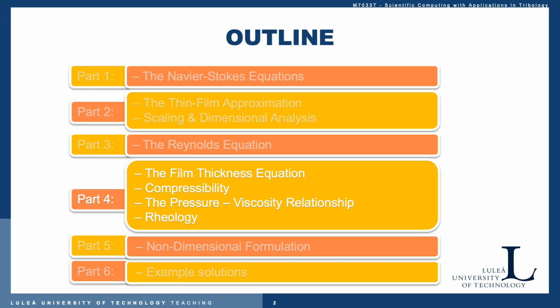As you know by now, the Reynolds equation is a lower dimensional model, so that for 2D flow it is 2D, and in coefficient form it reads like this, and here we have the time-dependent variant for incompressible isoviscous flow in Cartesian coordinates.